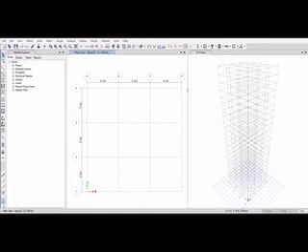So click on add new property and select auto list options. Change the property name to auto select beam. Change the material type to concrete and select all the defined beams and click on add. So all three beams we defined are selected in the auto list. Click on OK. So here we defined the beam and the column for different sections.